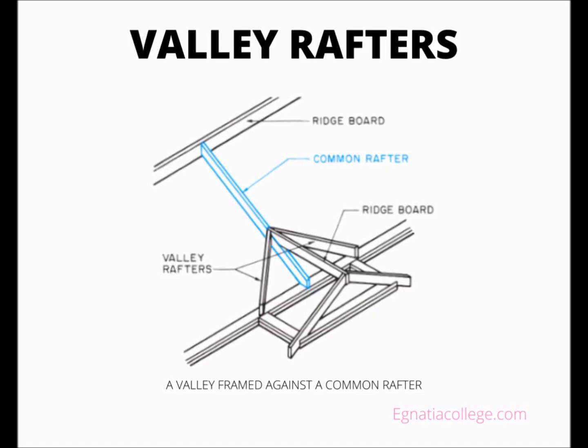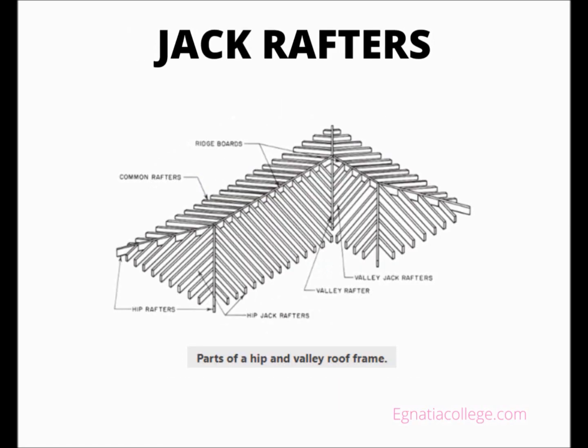The most important function of a roof is to prevent water from entering the structure. One area where leaks sometimes occur is in valleys. If the valley flashing is not wide enough for the pitch of the roof, wind-blown water may be forced under the roof covering and run beneath the flashing. Most roofers also apply a self-adhering ice and water barrier to the valley area before installing the flashing. The ice and water barrier provides excellent additional protection against leaks in the valley.